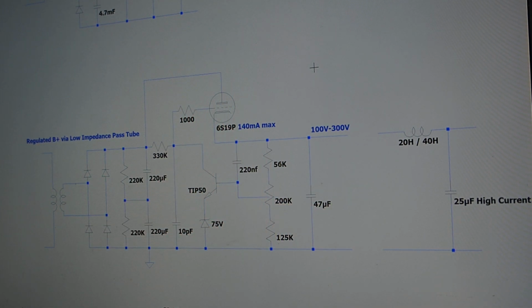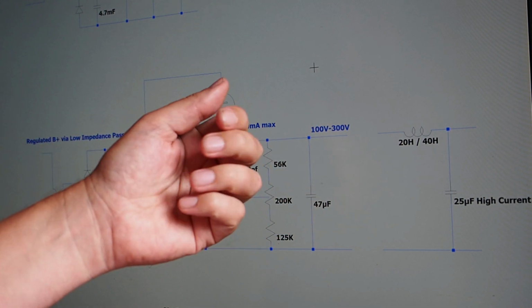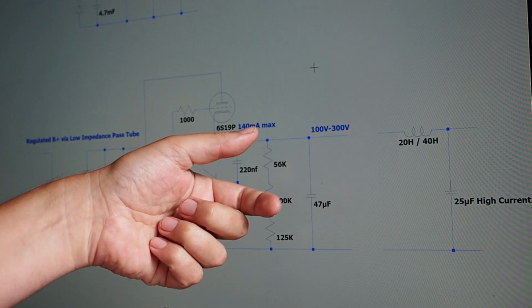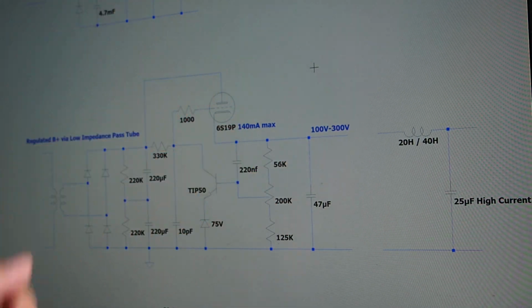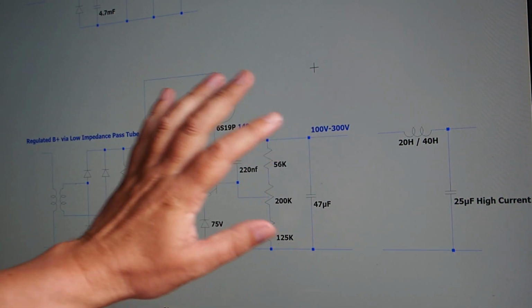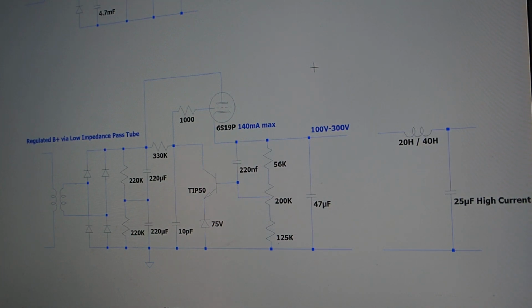But I still find that if I have a single-ended amp and there's a huge fluctuation in power draw, this is suboptimal. And so in my application of my amp, if you think back to part 2 in this series, I'm using a driver stage that is 9 milliamp, and then as the output stage I've got a differential amp which is near constant power draw. So that is where I think this circuitry shines, and not with a single-ended stage.